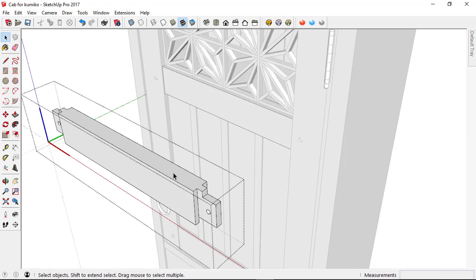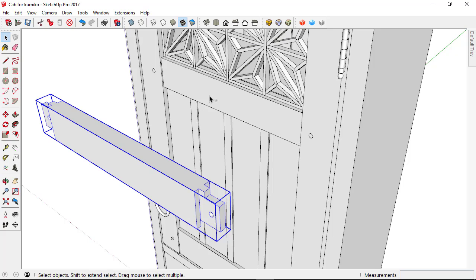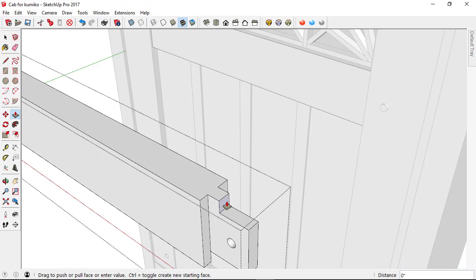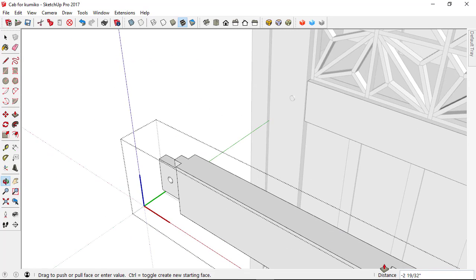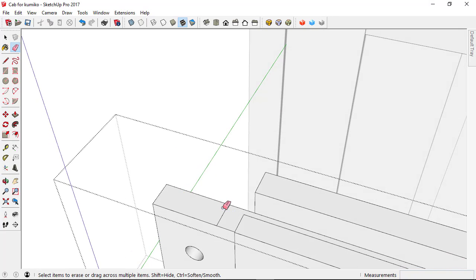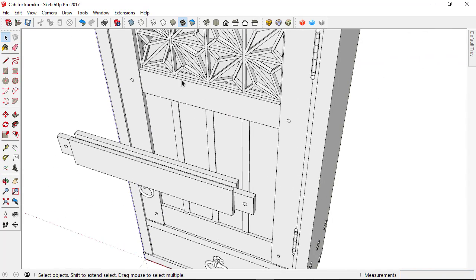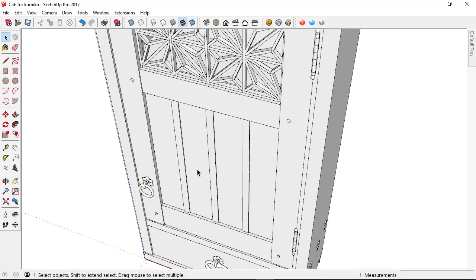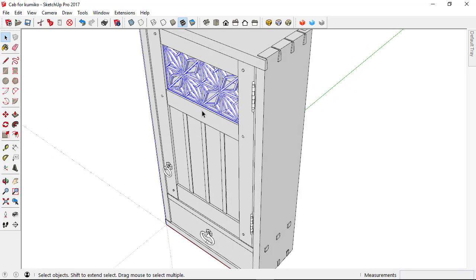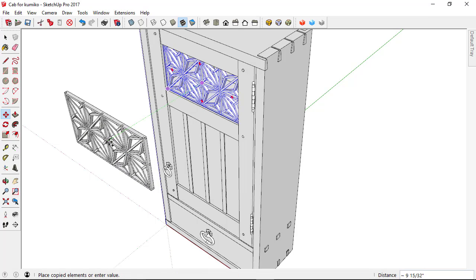Let's go ahead and put in a groove in the top. Actually, let's do this first. Make unique. I don't want to put a groove in the top rail, but I want it in this middle rail. And so we go to there, and to there, and there, and if there's any geometry left over, we just delete that. There we go. So that rail has also got that. Now I'll just pull a copy of this out. I know the groove is a 1/4 of an inch deep. So let's work on a copy of this thing from out here.